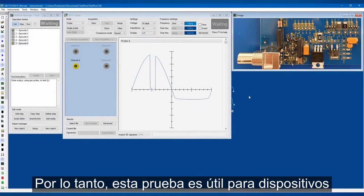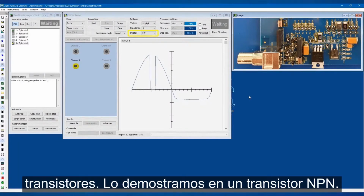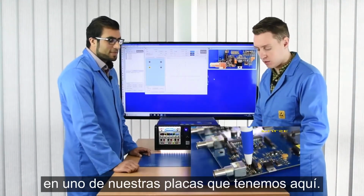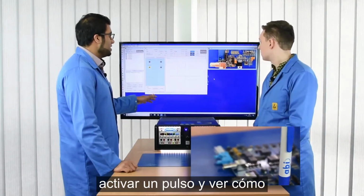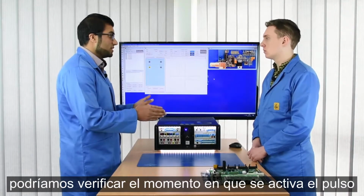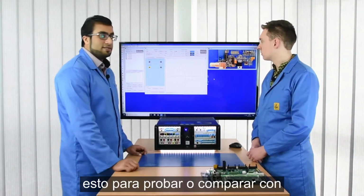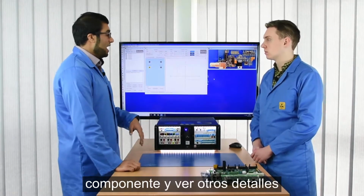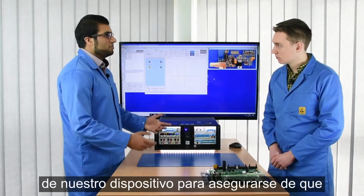So this test is useful for gate-activated devices, for example, transistors. You demonstrated on an NPN transistor, is that right? Yes. Okay. I used the transistor on one of our boards we got here. Sure. So what this allows us to do is trigger a pulse and see how our device responds. We could check the voltage, we could check the time the pulse is triggered, we could check the time the device is activated, and we can use this to test against or compare against the specification, to compare against another component, and to see various other details of our device to make sure it's operating as it should.